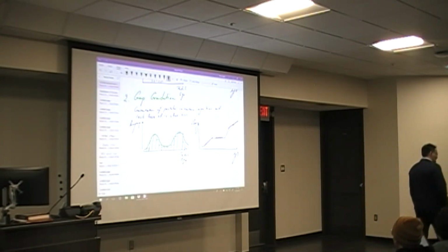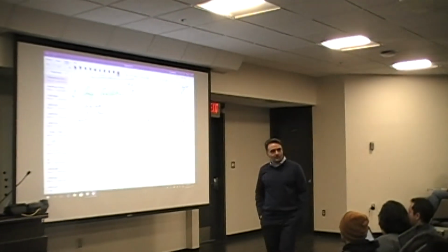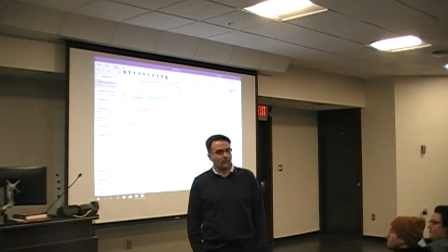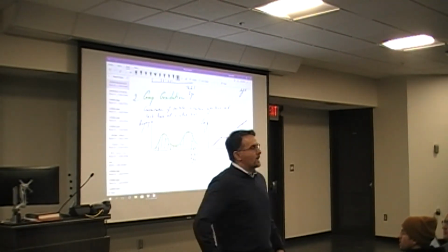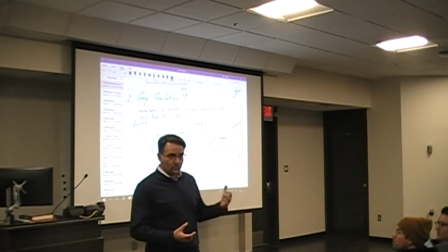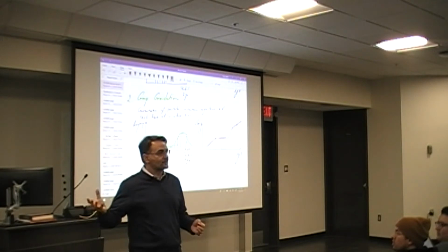What happens on a farm-to-market road with 1 or 2 inches of asphalt and, say for example, 3 or 4 inches of compacted granular layers, if one of those heavy pieces of equipment weighing over 200,000 pounds passes over? It will damage the pavement. What happens to the foundation, which is the compacted soil there? Excellent, it would crush the aggregates, right?